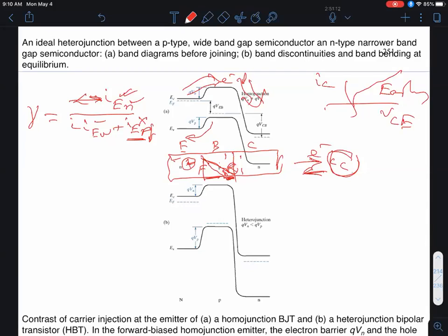But the same thing happens in a semiconductor. There's a maximum amount of dopant atoms that you can dissolve into the semiconductor. That's called the solid solubility limit, okay? And the emitter is generally doped up to that level. But on the base, you'd like that to be optimized to make it low enough to increase these components so that the emitter injection efficiency is high, but not so low that the base depletion region extends so much that the Early effect is very pronounced. And also you don't want the base doping to be so low that the base series resistance, RB, is too high, okay?